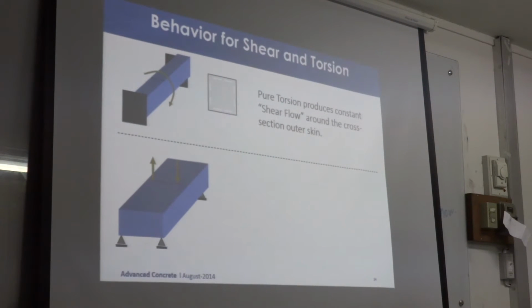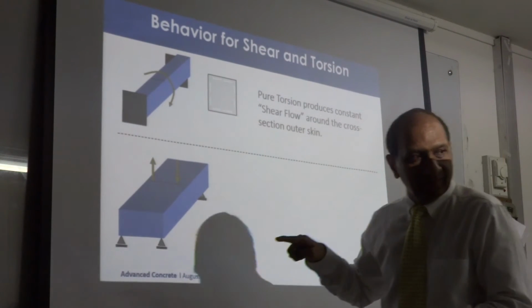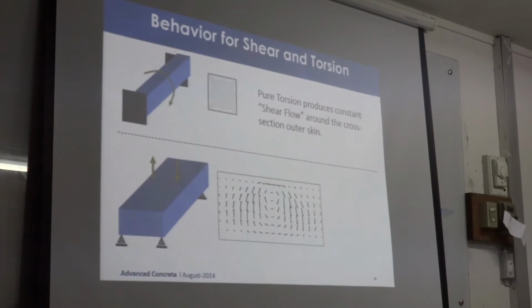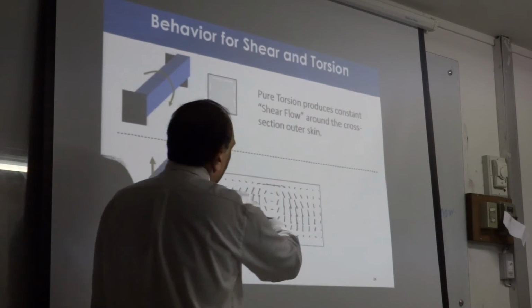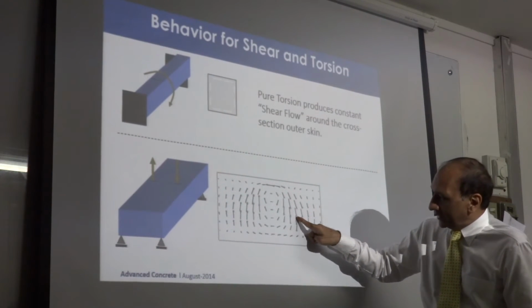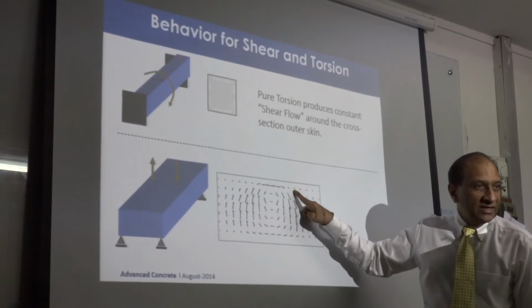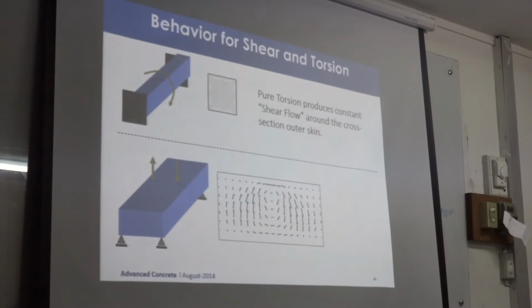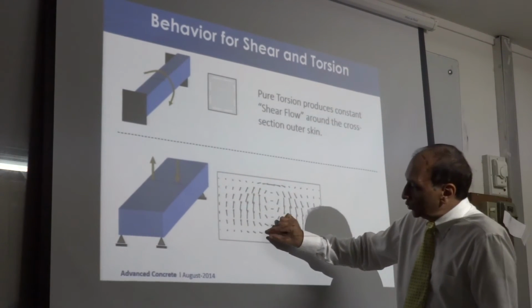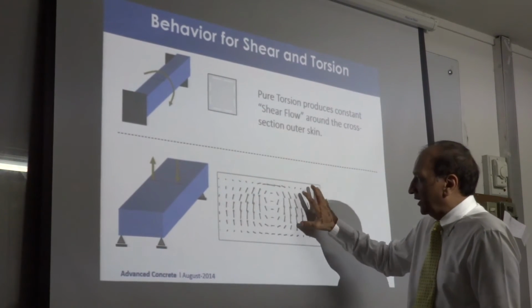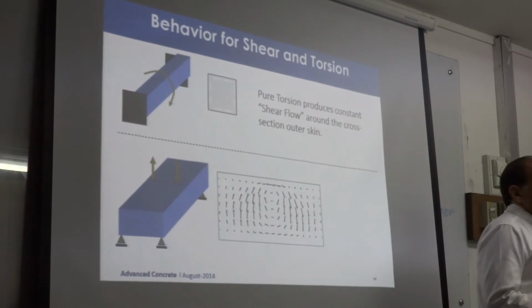Why? For bending. I'm asking why? No, no torsion. I'm just saying for pure bending moment, only bending moment, we also may need the reinforcement in the middle. Why? Normally called ASW. So we have AST, ASC, let's say the moment is positive, tension at the bottom, compression at the top, and ASW in the middle. Why do we need ASW?